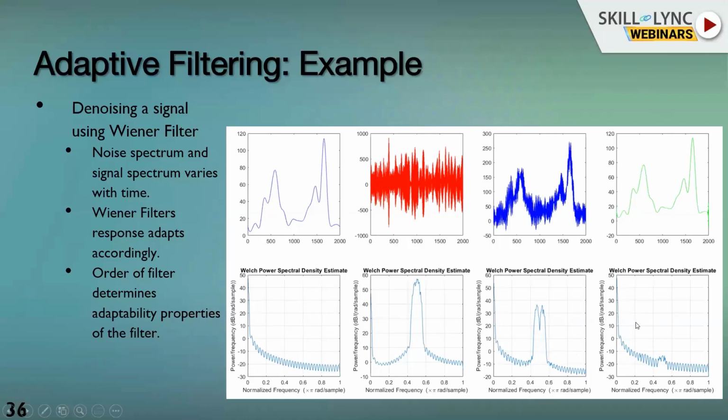And if we have the capability of implementing a higher order filter, then we are able to retrieve the original waveform. Our retrieved waveform is very close to the original waveform, and that means that even with changing background noise and all the noisy behavior happening in the background, the laptop or whatever device is implementing this Wiener filter can deliver the speech signal very cleanly and accurately, as shown in this illustration.